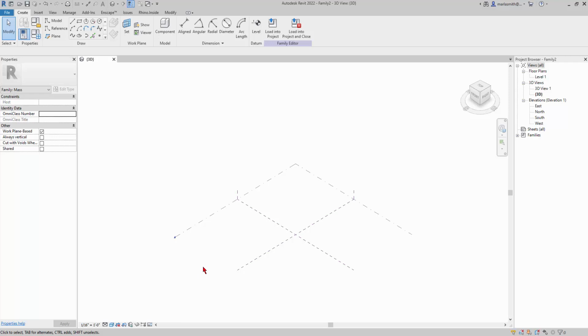All right, so this twist tower, the height of it is driven by a vertical line. So basically what we're going to be doing, the order of operations is we're going to host something like a piece of geometry, then we're going to host another piece of geometry and another piece of geometry to that and build up this hierarchy. So think of like animation rigging, like the rigging of an animation figure, but we're actually animating a sort of mass of a building. So the first thing I want is a vertical line to control the height.